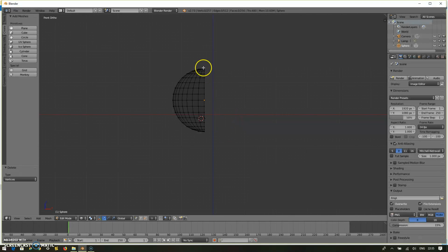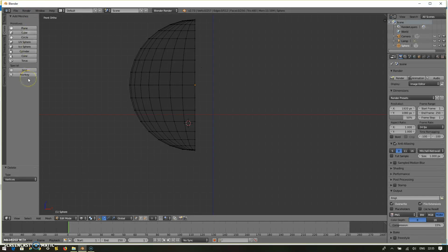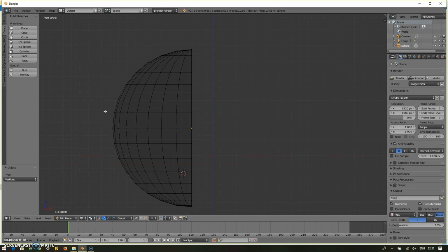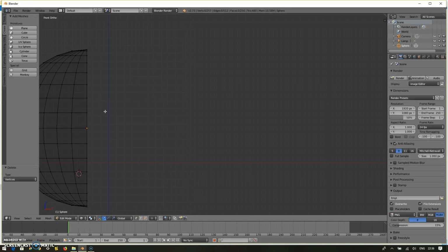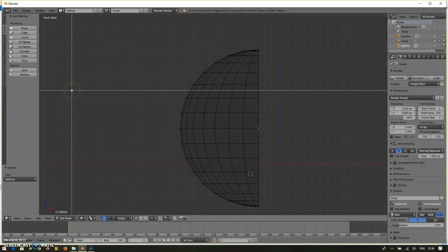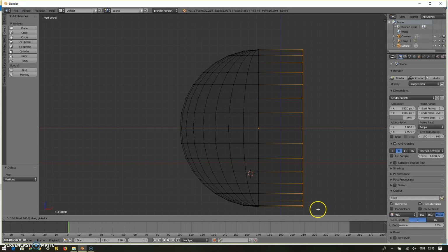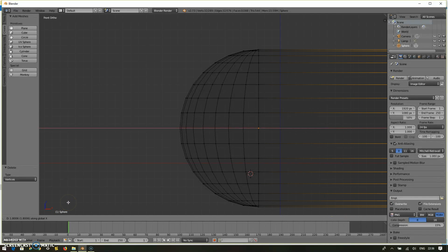Right, so let me teach you how to extrude this half sphere with only one set of vertices at the middle. Let me select only the middle. Let me zoom in a little bit so that you can see clearly. Now I'm pressing Shift, zoom in and out, so it's like a pan vertically. If I press Control, it moves horizontally, so be careful where you want to keep it. Now I press B and choose only this half. Okay, so I'm pressing E, and then I want to extrude only on the x-axis, so you can see I'm just extruding it. Okay, right, that should be fine.